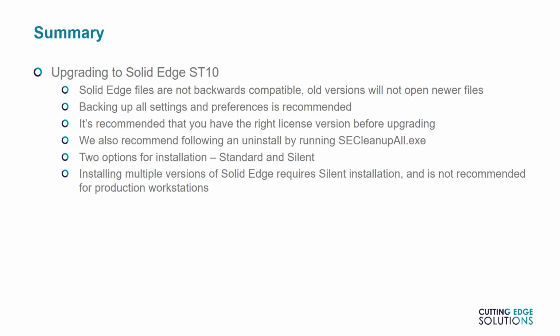It's a good idea to clean up your install directory before installing ST10 with SE Cleanup All. And we've also covered standard and silent install procedures and why you would use one over the other. And finally, bear in mind that it's only possible to install multiple versions of Solid Edge with the silent install procedure, and it's not recommended that you do so on a production workstation.